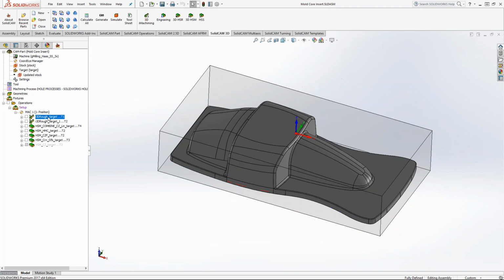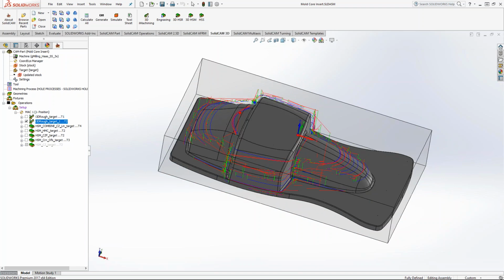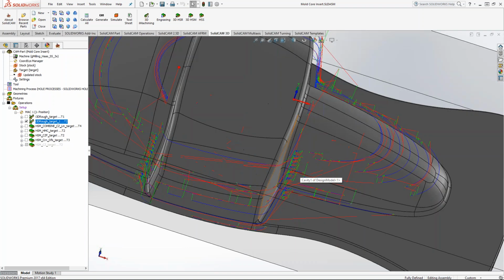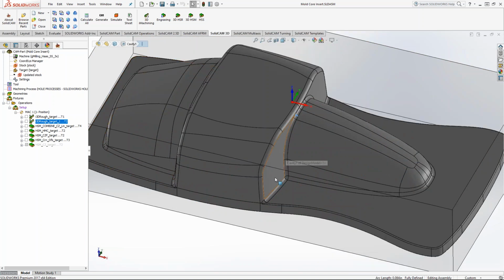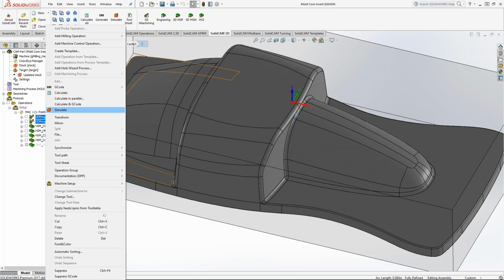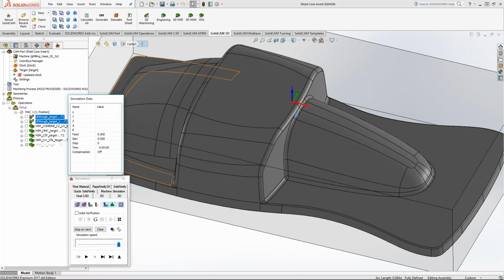I came back with the 1/2 inch bull nose again with a 60 thou radius, and I think I came back with a 1/4 inch with a 30 thou, to work out these corners over here too, because if I recall, these are like 60 thousandths fillets around here. So I just wanted to get some of that corner material out before I started doing the finishing with some other tools. And we'll just run through a quick simulation on these 2 3D machinings.